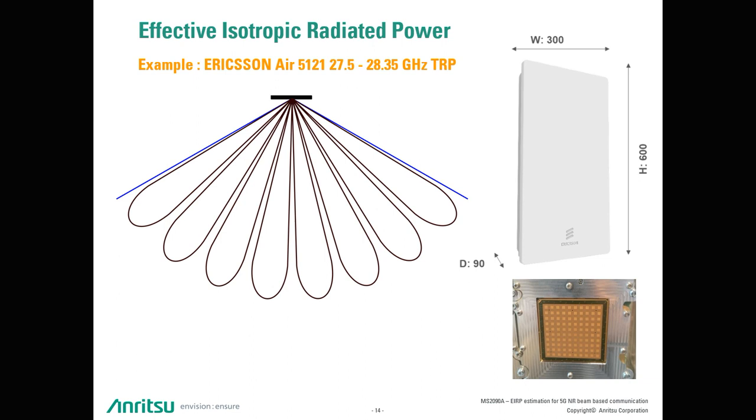What kind of antenna can we consider in practice? What kind of beam widths and what kind of gain do we see in the field? For the moment, we don't have a common answer to this question, because no network is really in commercial operation so far, and the antenna manufacturers keep information often very confidential. But since spring 2019, beamforming antennas in the sub-6 frequency range 1 and trials for the frequency range 2 at 28 GHz are becoming visible.